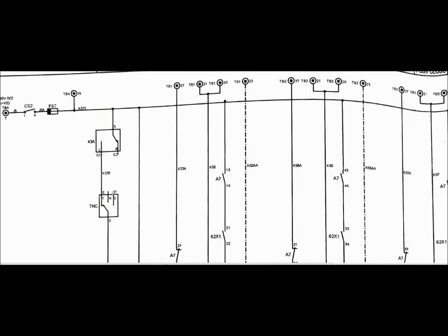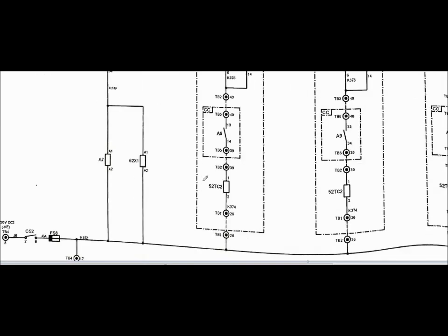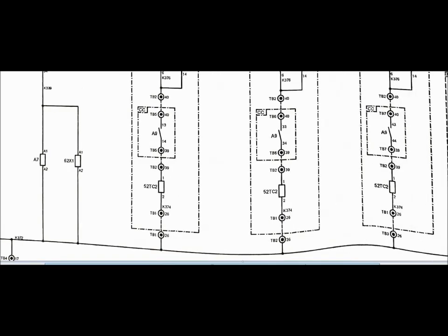Now, 43A is the local remote selector switch for local tripping of the circuit breaker. This selector switch must be in local position. Now in the trip circuit we can see there exists the A9 contact. These are the circuit breaker SF6 lockout contacts.